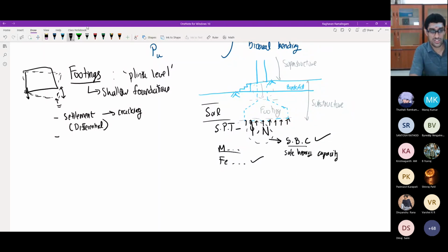So you will start having shear cracks. I will call it that, you'll start having diagonal cracks in your walls. Whenever you see a crack like this, it means somewhere there is differential settlement happening. And because of this, of course, your beams and columns also may start having cracks. So anyway, this is known as differential settlement. It happens if your SBC is not so good.